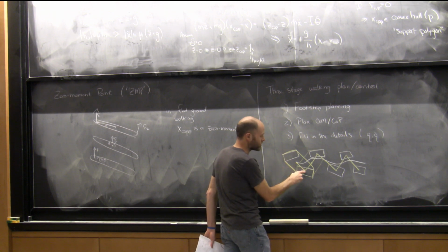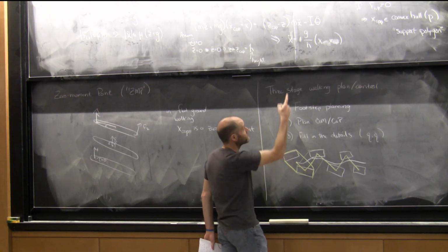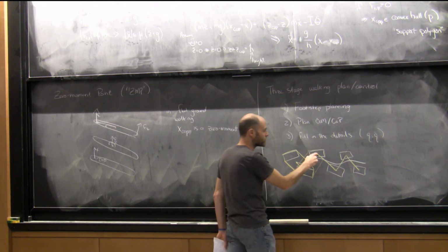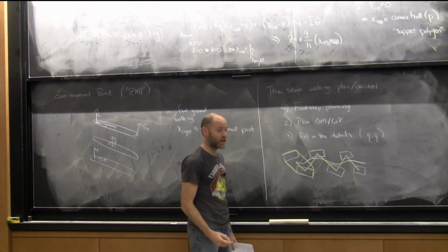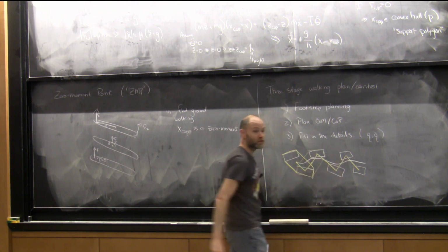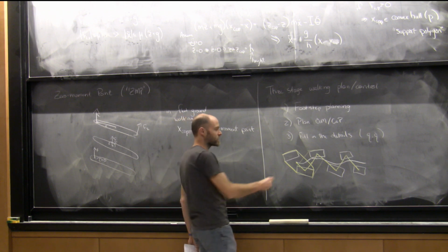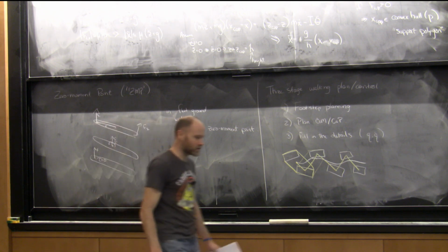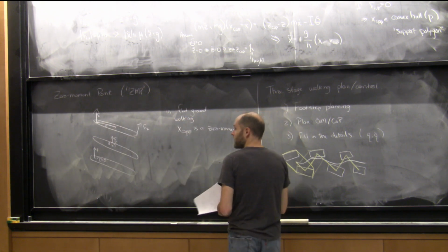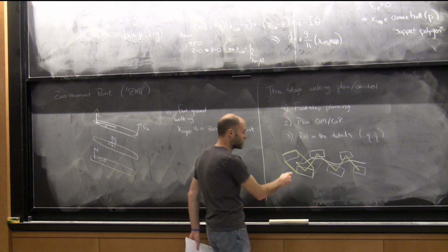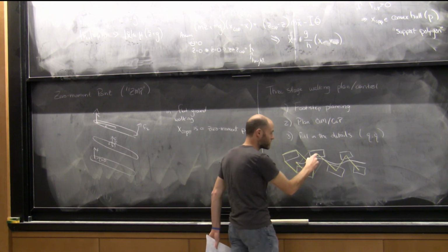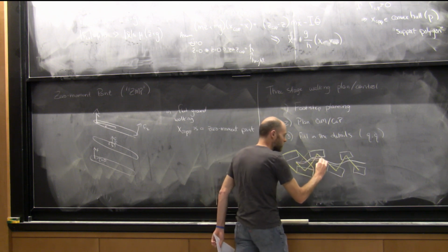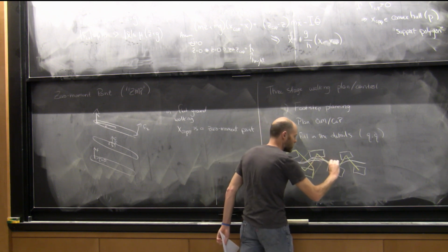But the old way to do it here was that, because of these linear relationships, because of this polygon constraint, it's easy enough to write down some feasible center of pressure trajectory, and that implies a center of mass trajectory. And the interesting thing is, if you wanted to walk through the same footstep plan but faster, you run the same equations, and the center of pressure could go through the same points, but the center of mass actually moves. It changes the center of mass trajectory if I'm going faster.